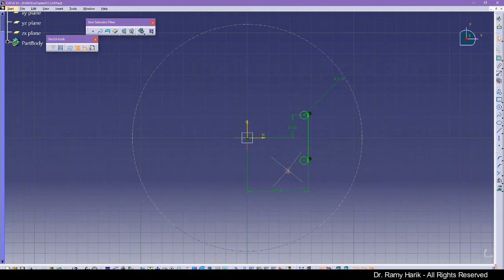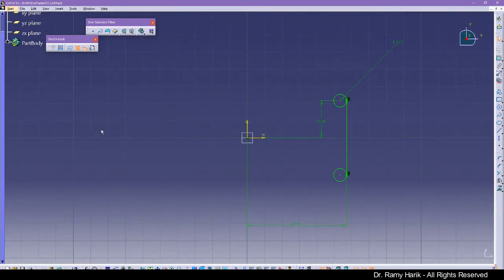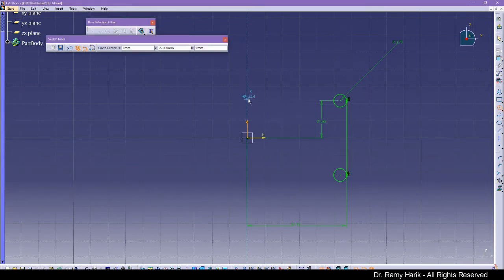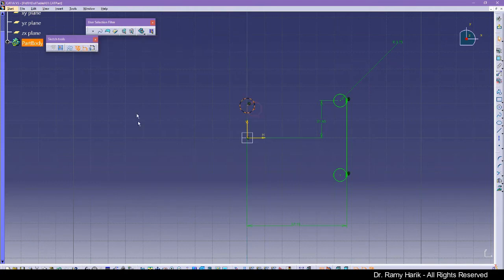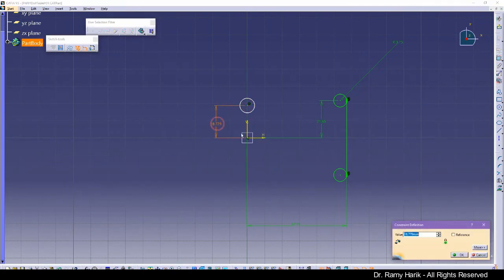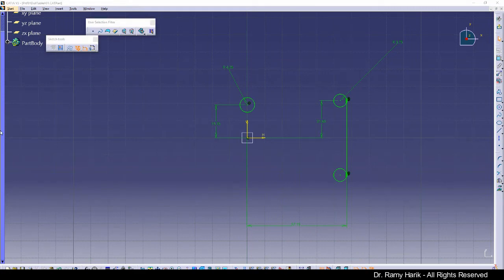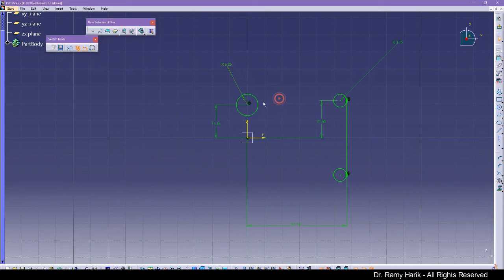Now we do have a circle, and that circle in the middle has a radius of 6.25. It's an arc, but I'm gonna go ahead and create a circle for now. The center of that circle is at 19.15, so I'm gonna click here and create the circle. Then from here to here we have the dimension of 19.15. Then we're going to put the dimension of the circle, the radius, and scrolling back here, the radius is 6.25. All right, so this gives us this circle.